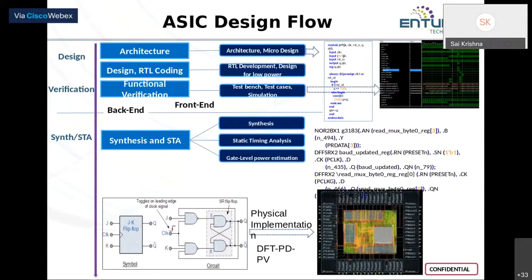So as you can see, once you are done with your RTL coding, you also write a test bench for it and simulate it to check the waveforms. So using Cadence tools, you can either check your functionality in the form of waveforms, or you can also use the console of your Linux environment to directly look at the values in numbers. Okay. So once that is done, you go for synthesis and also perform timing analysis.